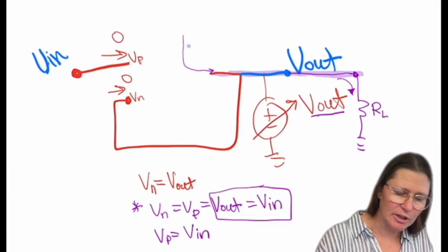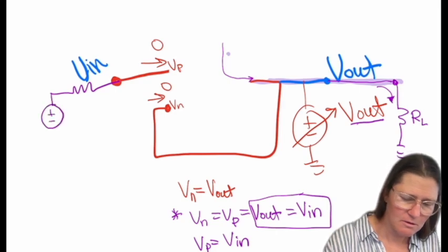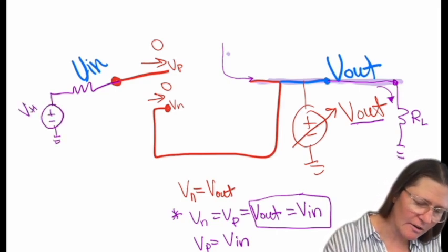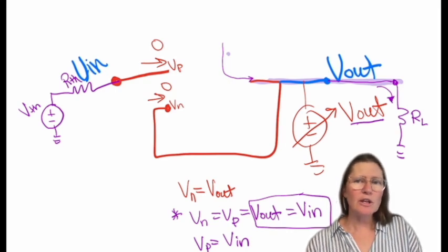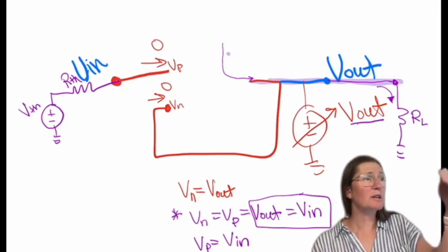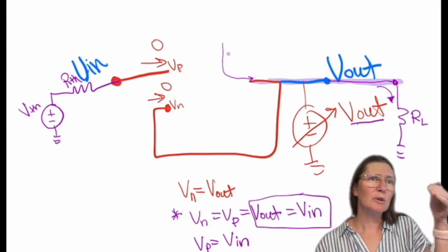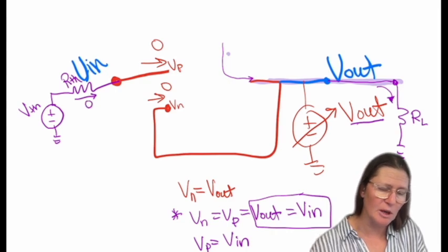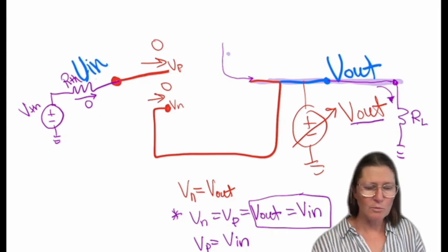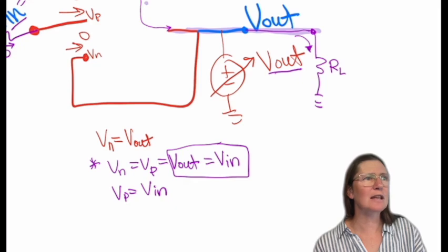So if I put my VTH here, with that parasitic effect of resistance RTH, now there's nothing to divide down and become a voltage divider, because that's a floating wire going into the op-amp. Do you guys see that too? Because there's no current going into that resistance, there's no voltage drop across this parasitic. And so my Vn is equal directly to my VTH, which equals my output, and I can keep it exactly at that same value.